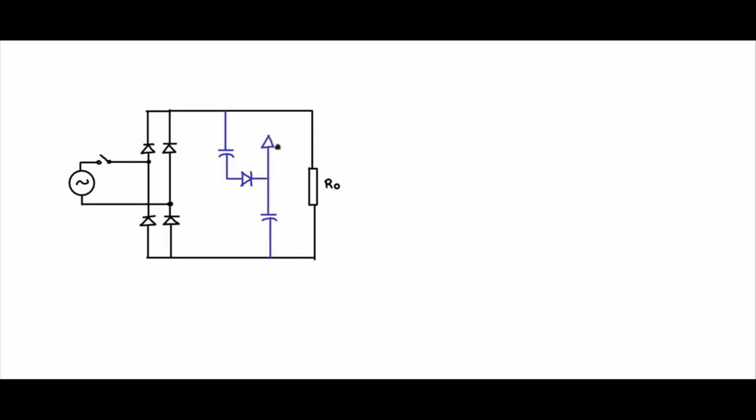You put a diode in this fashion. So this diode will give this capacitor a chance to discharge through the resistor in this fashion. And if I put a diode here, you will see that this capacitor can independently discharge through the load in this fashion. So while charging, you will see that the charge path is only in this way.